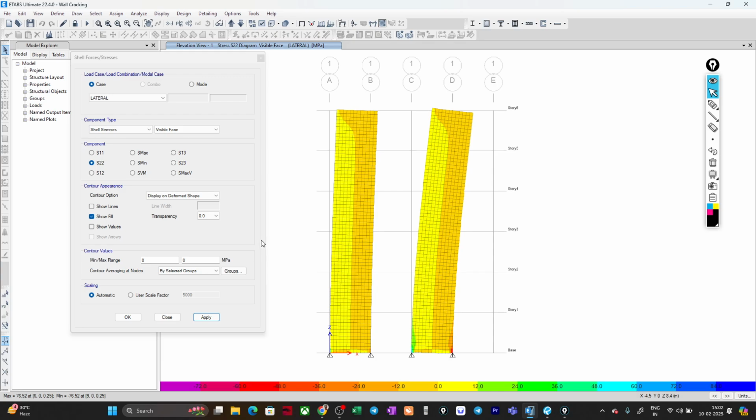Now you see here, okay, S22, fine. Now if you see, the stresses here are changing. You can see the values here. The range of values is given, so we can see these stresses. Now how do we understand the limit of stress, up to what extent we should consider 0.7 Ig, and up to what extent we should consider 0.35 Ig?